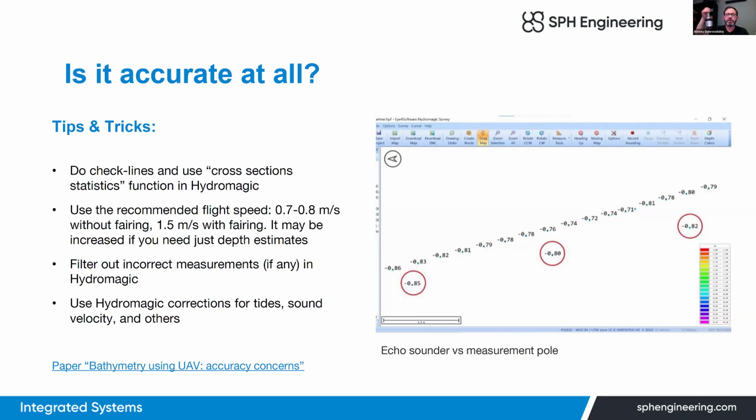It is the same because we use the same technological bricks. We do not use a cheap Chinese fish finder as a sensor. It's a survey grade high-end echo sounder. We use very high quality RTK receivers on the drones with a precision of a few centimeters. And we use standard workflows for data collection and data processing, absolutely standard. The only difference is that the platform for the sensor is not floating, it is flying 2 meters above the water surface. All the rest is the same.